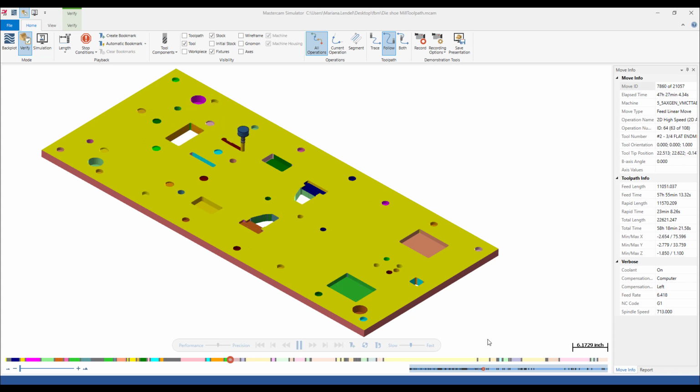The main advantage of the feature-based milling is that it takes a couple of minutes to set all the parameters, and you get the entire part machined without having to select each individual feature and set up a toolpath and set up the parameters for each of them.